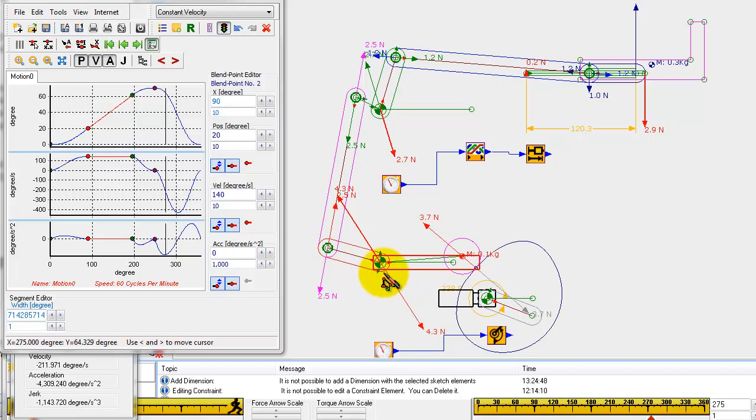The clue lies in the bearing force of the follower rocker, which seems extremely high. This tells me that the cam is generating too large a component of force against the bearing in order to generate sufficient force to drive the load inertia. In other words, the pressure angle of the cam is probably high.